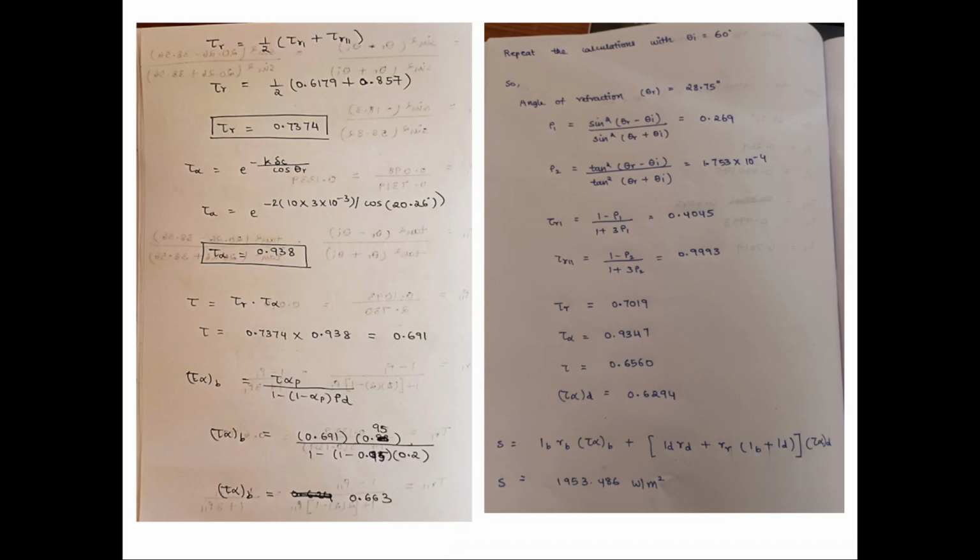One is the losses that happen within the system, and other geometric constraints decrease the value of the solar flux absorbed by your absorber plate in the flat plate collector, because of the convection losses and re-radiation losses that happen when it goes from the cover to the absorber plate.